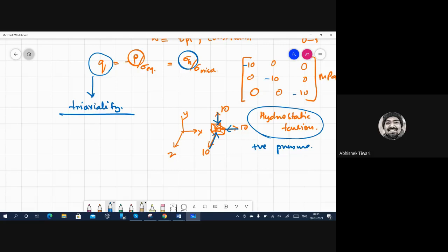So you can also have an understanding in this case that it is actually a ratio between how much hydrostatic stress is applied in terms of how much shearing is there, because sigma Mises actually represents the shear stresses in 3 dimensions.